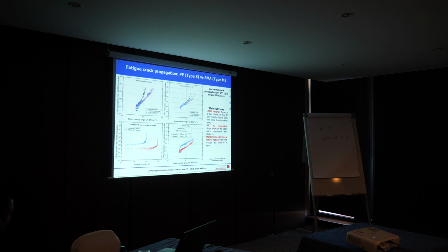In fact, if we analyze the results obtained by DIC, but also by our analytical model, they lie on a straight line. So it means that they can be described by Paris law.